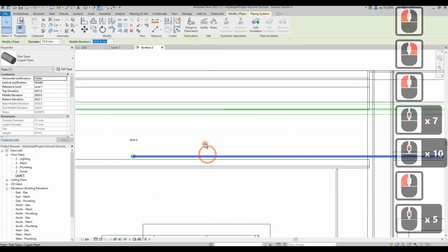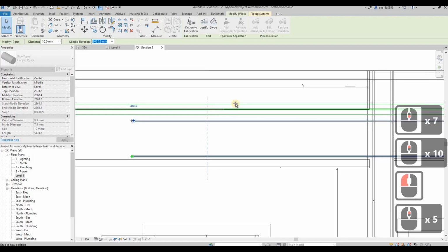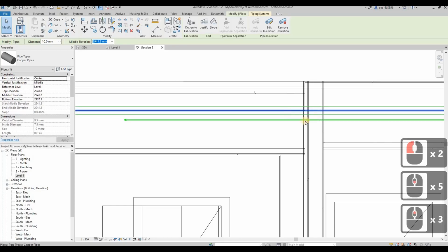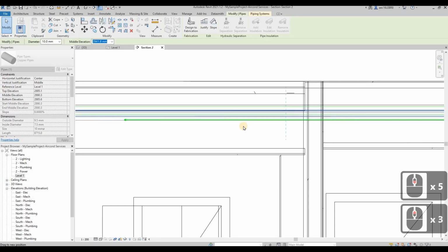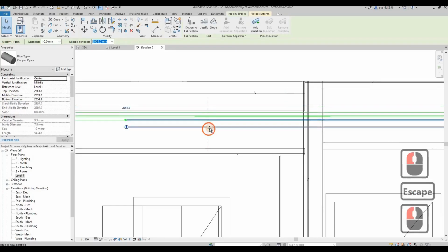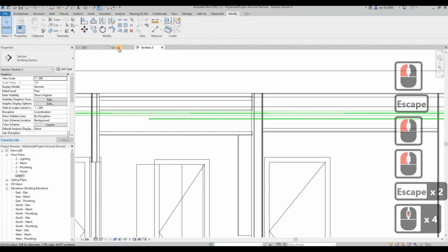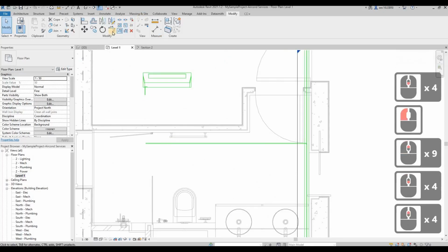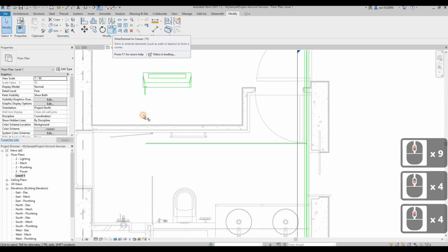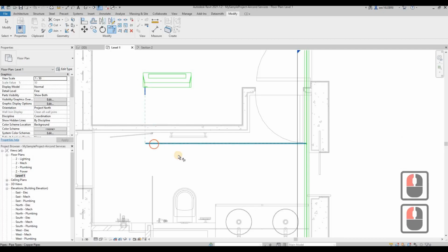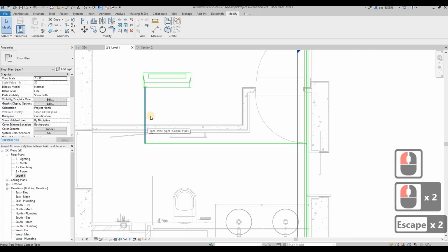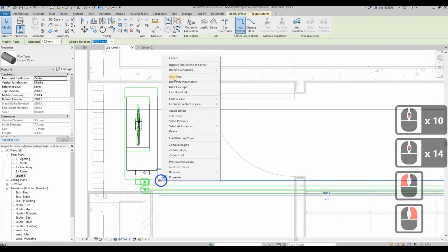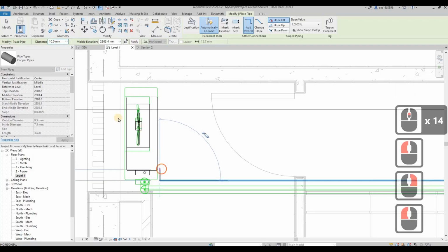So this is your piping for the master bedroom. This one needs to be lower down, of course, or just lower down here to avoid any clashes. Somewhere like this, then you go to here. Then you connect your pipe by using this trim extend corner. Also okay. Then you draw your pipe back to this outdoor unit here.